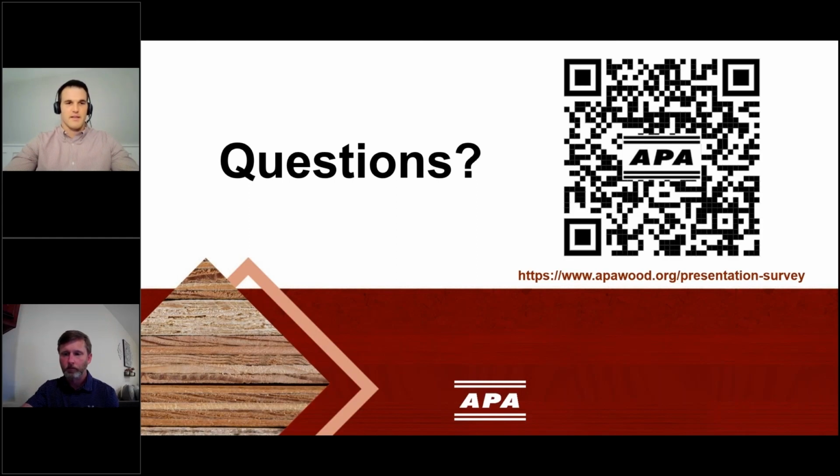The APA panel grade, span rating, bond classification, performance category, those are probably the most essential things to include. Our engineered wood construction guide, which is Form E30, gives a little bit more detailed guidance on how to properly specify and order wood structural panels. So if you want to make sure you're including all the possible things that you can, go to the engineered wood construction guide and check out that panel specification page.